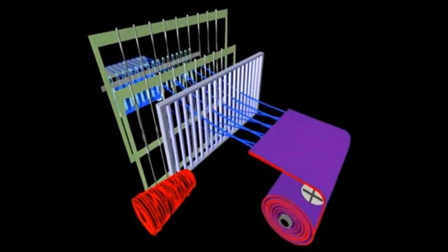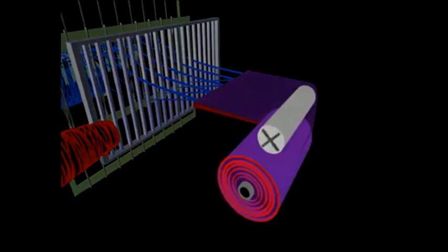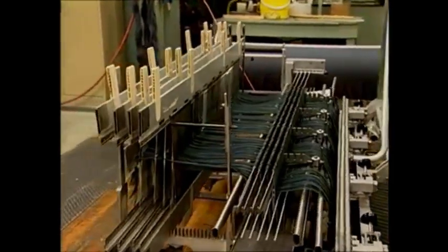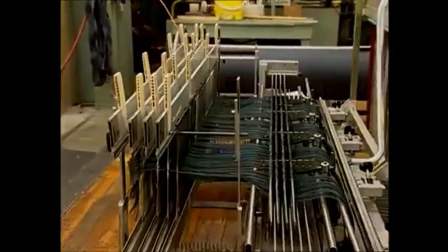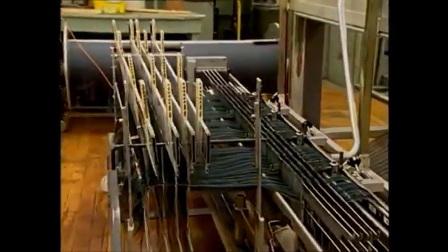The cloth now winds over the take-up roll, sometimes called the sand roll or press roll, which, when combined with the let-off of the loom beam, controls the number of picks per inch in the fabric. Finally, the cloth is rolled onto a cloth roll. The threading or drawing in of the yarns can be done manually or automatically on drawing-in machines. Of course, manual drawing in is much more time-consuming.